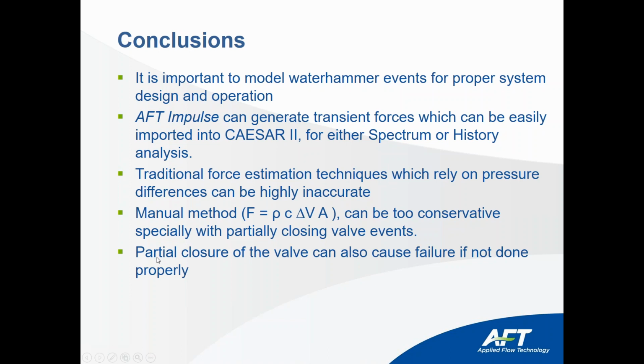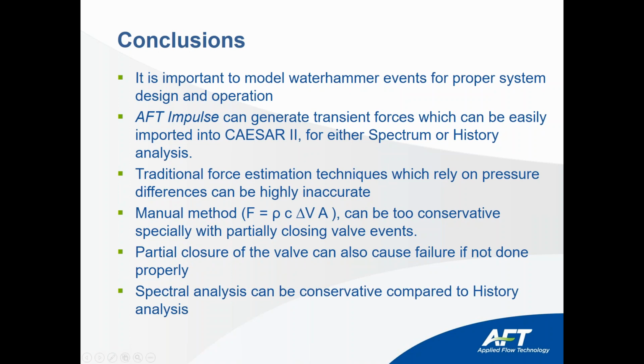Partial closure of the valve can also cause failure if not done properly. People tend to think that the failure due to Waterhammer occurs only if you close the valve totally. And as we saw in the example, if you close a valve partially it can also cause problems. Spectral analysis can be conservative compared to history analysis, and we saw the spectral analysis gave us a result of 22% of failure against 18% for history analysis.